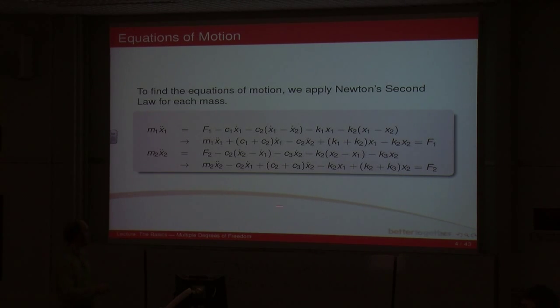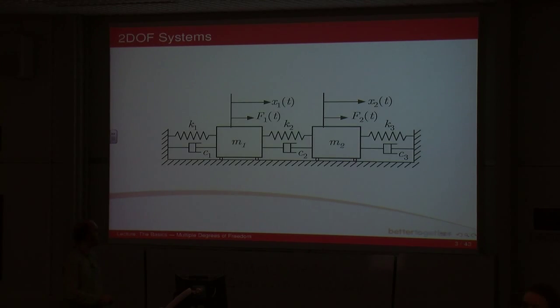Fortunately, we've got an equation for x2, which is the same thing here. Again, if it's between the 2 masses, then you have to include them both. Okay. So x2 dot minus x1 dot for that damper, and this one for the spring. So if we go back to the picture, if we look at mass 1, you've got m x double dot, okay, which is the inertia, equals this spring force times that displacement, and this damping force times that velocity. Okay, that's all contained within x1.